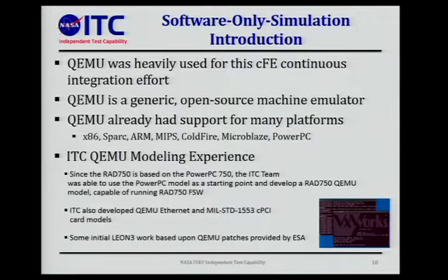To that point, though, we have modeled Ethernet in QEMU, a very common Ethernet chip that's used on a lot of missions. We have that modeled. And we just got the 1553 compact PCI card Summit chipset, if you're familiar. It's a very common 1553 chipset. We have that modeled in QEMU as well. So you kind of see here, if you put a bunch of these pieces together, you have a whole spacecraft that you can run under QEMU, and then throw in the flight software binary. You could have a system able to test all under an open source emulator.